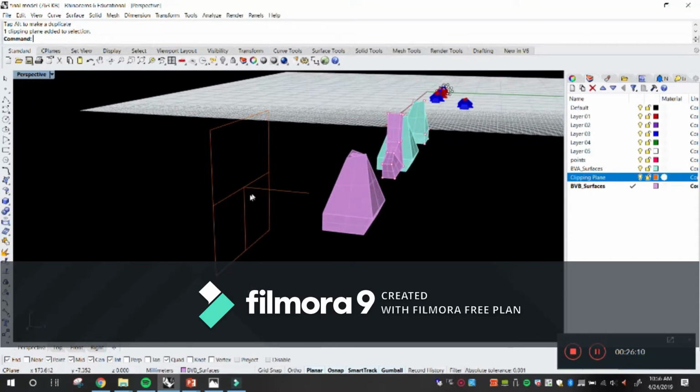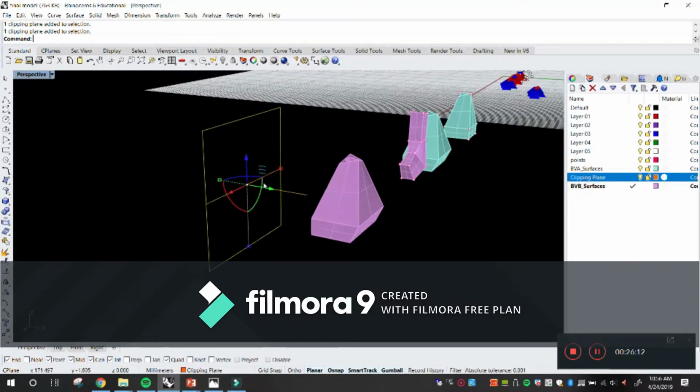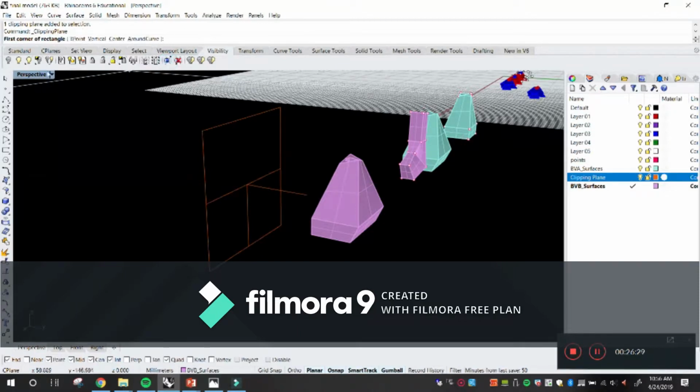Okay. So what was this called again? What did we draw? A clipping plane. Okay. So if you go up here to visibility, you have some tools, right? There's that one right there, add clipping plane, which is what we just did. First corner. Now, right next to it, you have disable and enable clipping plane. Okay. So we want to enable it.